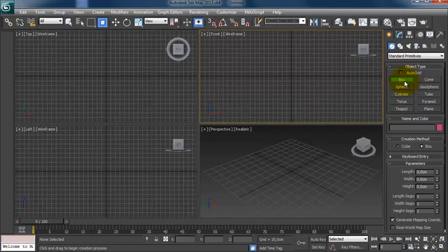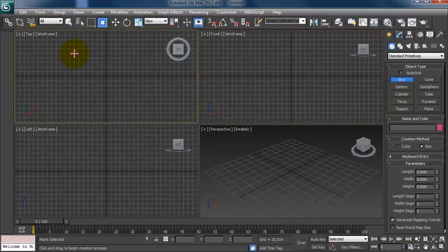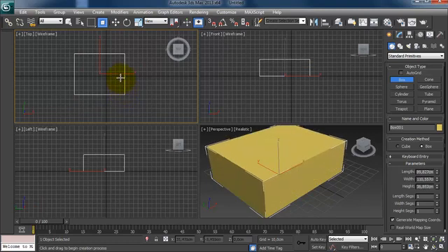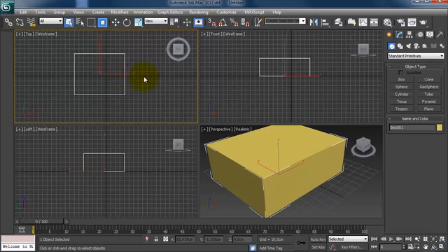By clicking on the box button, highlighted, and in the first viewport at the top right, click with the left button of your mouse, dragging it towards the bottom right to draw the base of the box onto the plane. Once you've reached the desired size, release the left mouse button. Now drag the mouse upwards and you'll see that the box acquires volume. Click again with the left mouse once you've reached the desired height. Finally, right-click with the mouse to finish off.